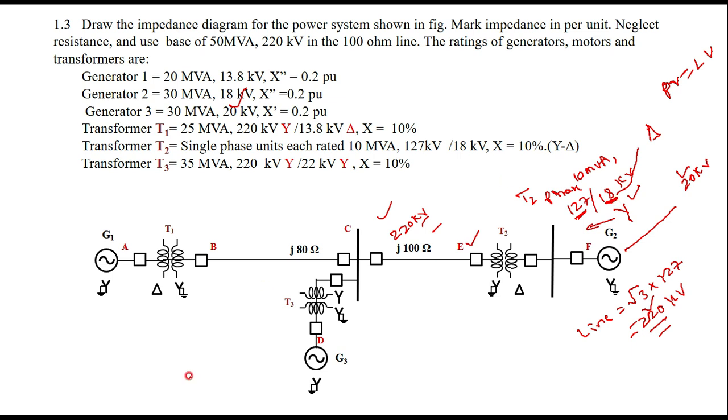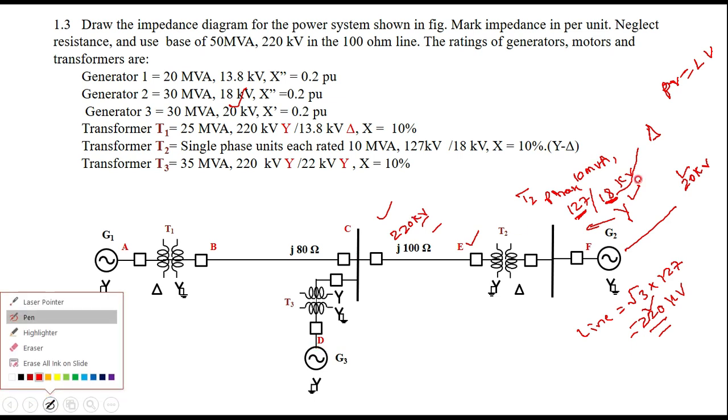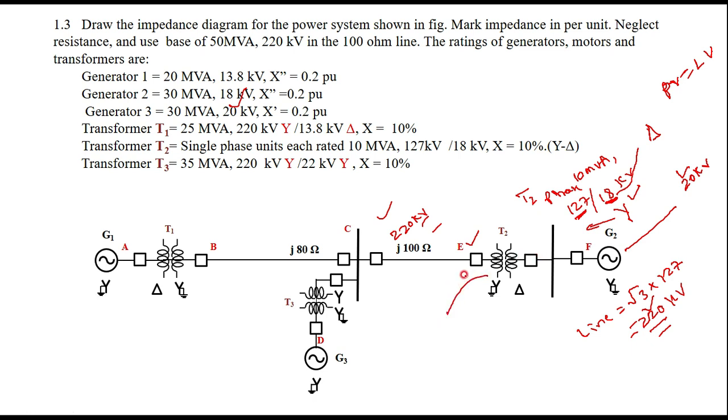Accordingly you have to write for three phase, and at the same time the rating of the individual transformer is 10 MVA. Therefore, this transformer T2 is 3 single phase transformers.